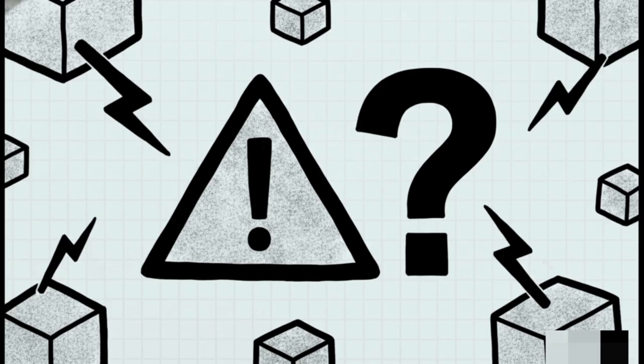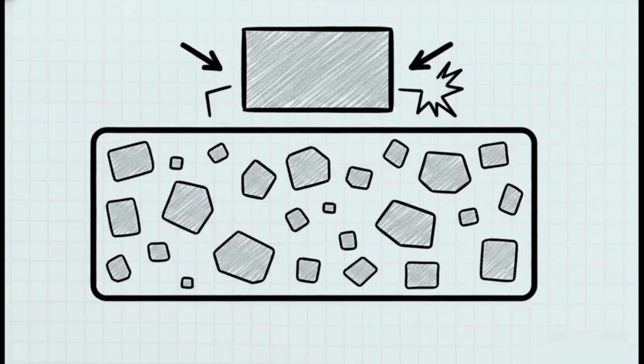If the heap allows us to just grab memory dynamically whenever we want, using commands like malloc, why is it practically a forbidden word in embedded environments? Honestly, it boils down to two things: memory fragmentation and determinism. When you dynamically allocate and free memory using malloc, it leaves these little gaps or holes of free memory scattered all over the place. Over time, you might technically have enough total free memory, but it's chopped up into tiny, unusable fragments. In a constrained embedded system with strict deterministic requirements, this fragmentation will eventually cause your memory allocation to fail, which crashes your entire system exactly when you need it most.